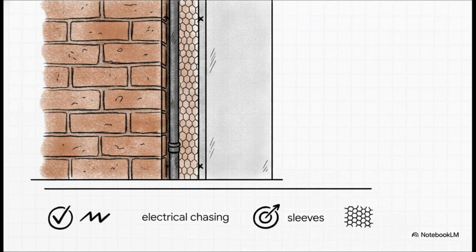Also, check your structural drawings to ensure chicken mesh or GI mesh is firmly nailed right at the junctions where your RCC columns meet the blockwork. Because those materials expand and contract at different rates, that mesh is literally your primary defense against differential shrinkage cracks.